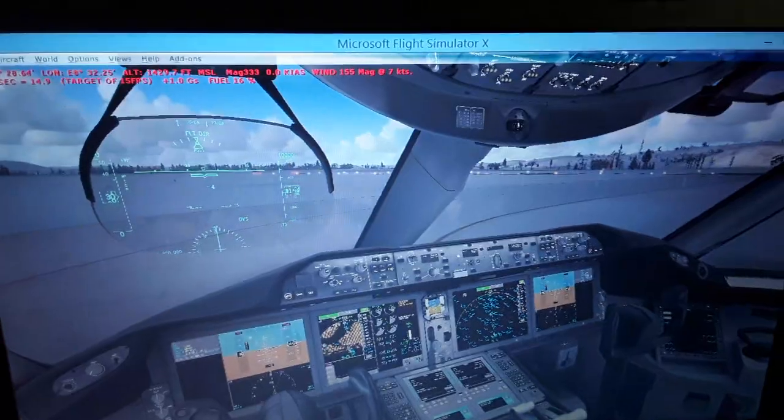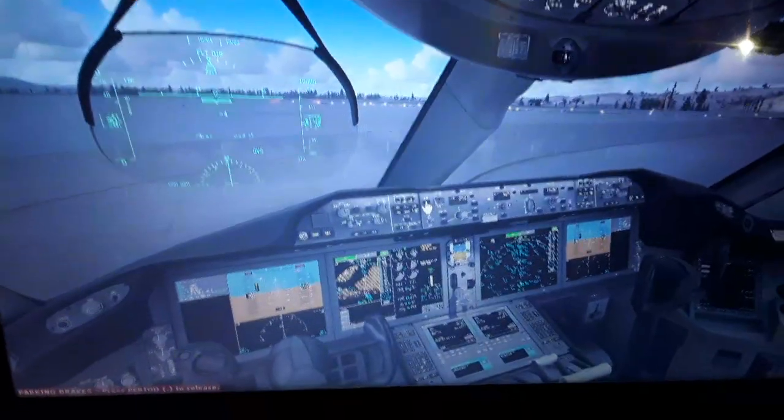International Airport, LSZH, in Switzerland. So you'll see how we're going to do that. So the ILS localizer will be aligned with that, for the horizontal localizer and the vertical angle of approach, the glide slope. So we're going to have also the ILS localizer crossbars. We're going to tune the ILS localizer using the flight management computer or manually using the radio management panel.